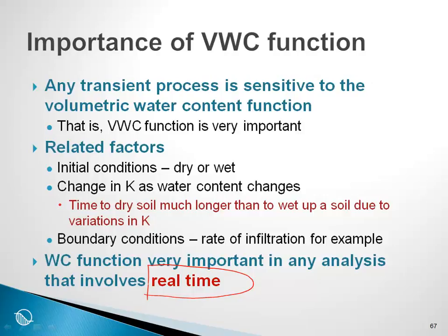So this brings us to the end of our discussion on how important is the conductivity function, and how important is the volumetric water content function. And the short answer, it depends on the conditions that you are trying to analyze and the type of process that you're trying to analyze in the field. We have seen that in some cases the functions are not important at all, while in purely unsaturated flow the functions are extremely important. So here is a brief summary of the importance of these functions, and hopefully it will give you a better comfort level on using these functions in SEEP/W.